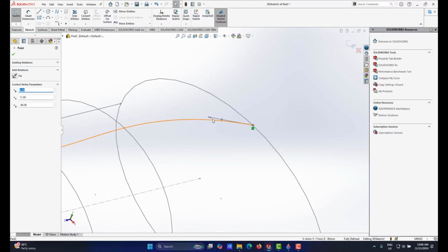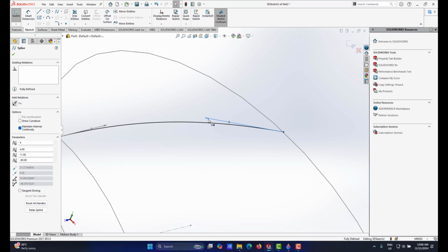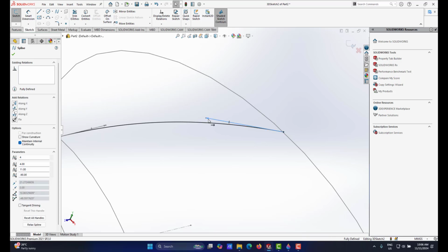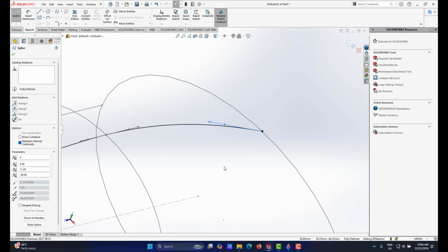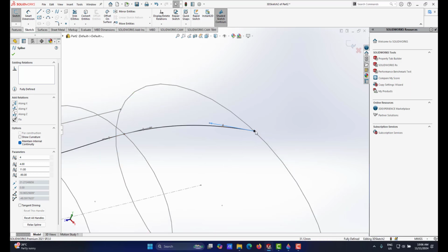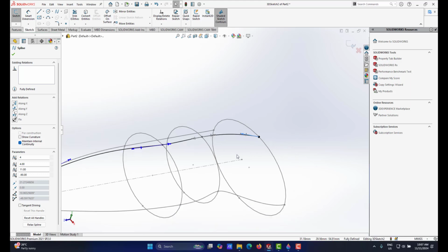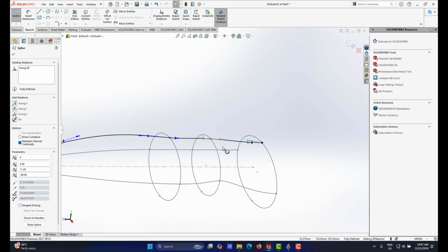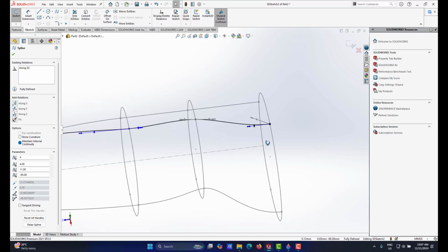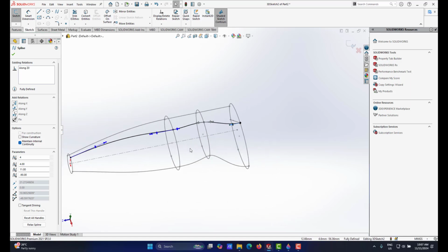All right, okay. Another thing that is important is the last point of my spline, the handle here. If I click at the arrow again, if you look under settings here, I have to make sure it is tangent along the Z direction. So it means that when you do the loft, it maintains the tangency in terms of Z direction. I just select here on the left, along Z. Along Z means it maintains the tangency to the Z direction. So this is very important.